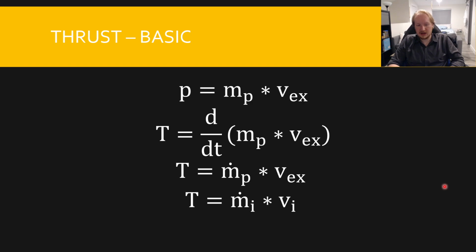And making this distinction, because those are pretty much virtually the same, is very important, because when we're talking about ions, they have charges, so we can measure their currents a lot more easily. And we can also use systems and tooling in place to measure their velocity based on how they interact with the electric field generated by the ions. So we choose to define them as the mass flow rate of the ions and the velocity of those ions because it's a little bit more accurate and a little bit more measurable.